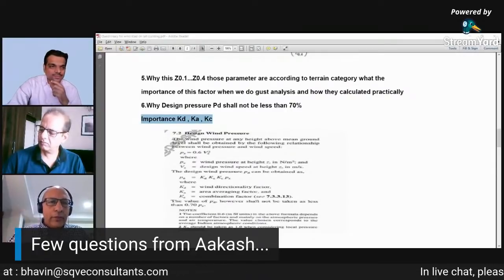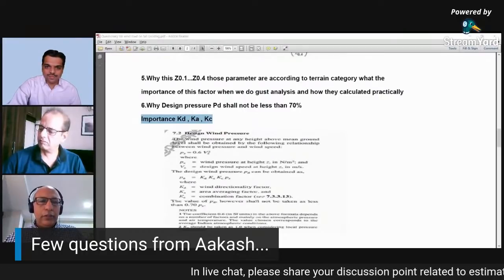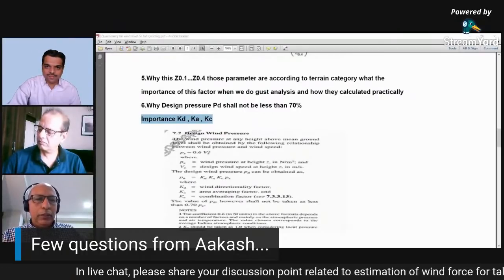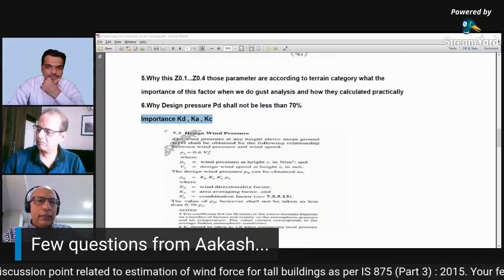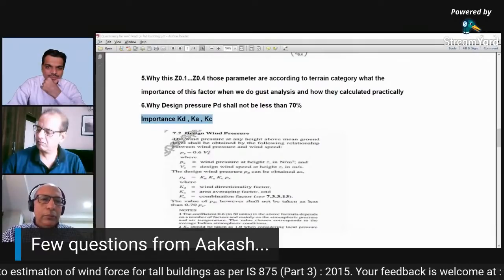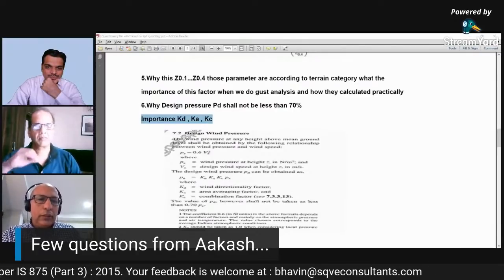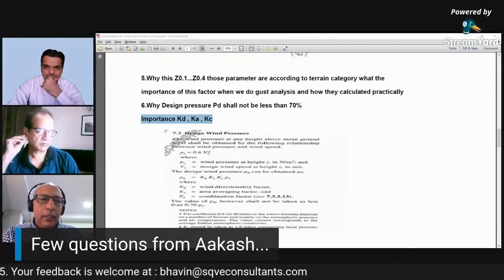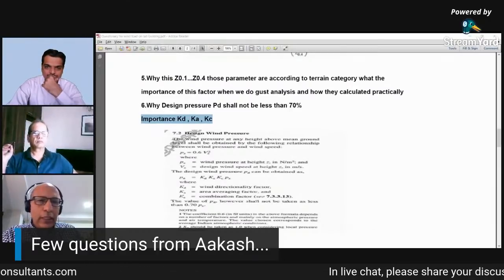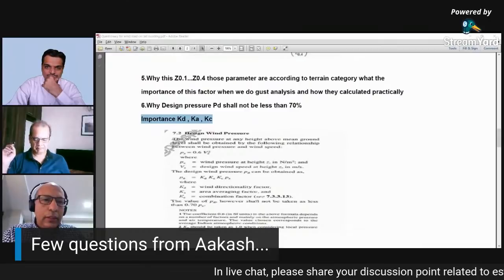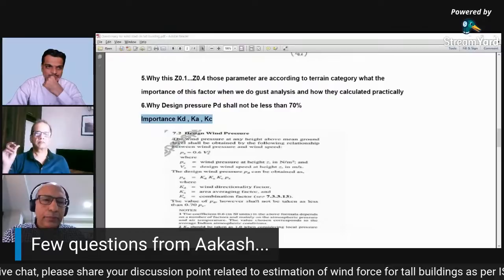The instantaneous peak averaged over this tributary area is never going to be as big as the instantaneous peak experienced by one sheet of cladding, for example, at any point on this tributary area. So it was established that we need to put a reduction factor for these large members, so we don't over-design them. This is the background to the KA.